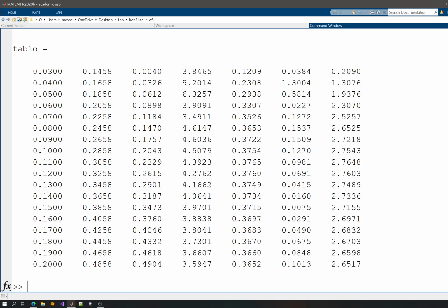So in order to accomplish that, I might combine these two. Since I have normalized them, this process of getting rid of the units, I can just have some neutral values that will represent a percentage. Now I can combine settling time, which is seconds, and overshoot, which is percentage. I can't combine apple and something else. I should combine apple with apple, which means that they should be of the same type.